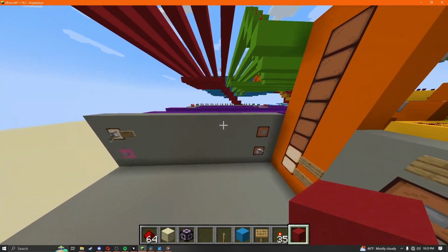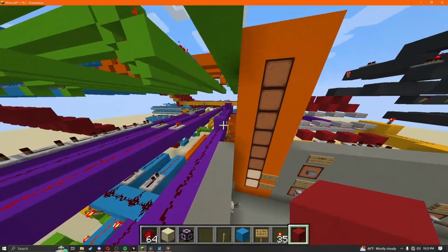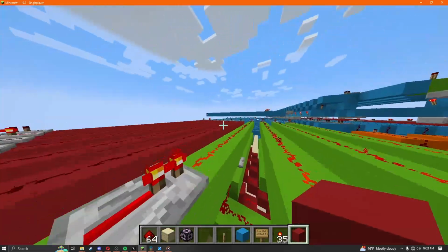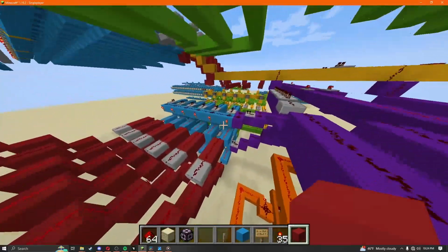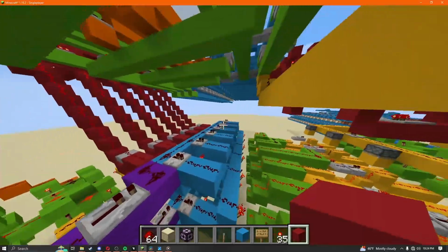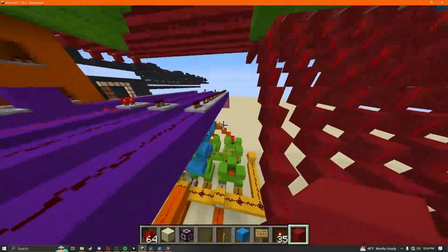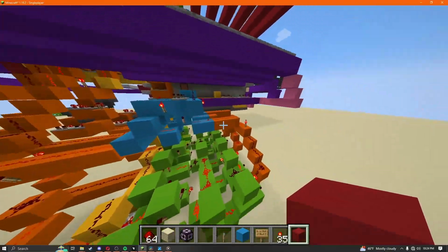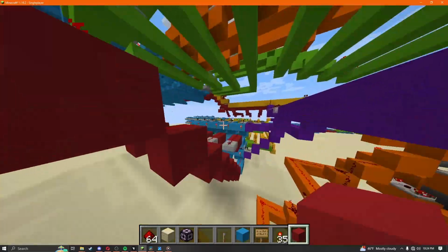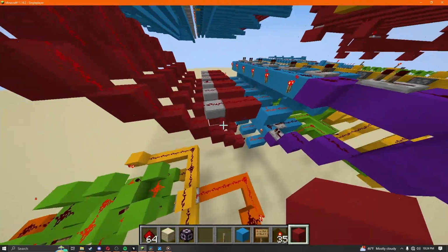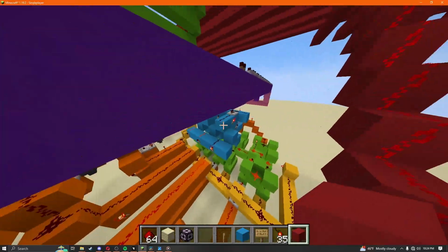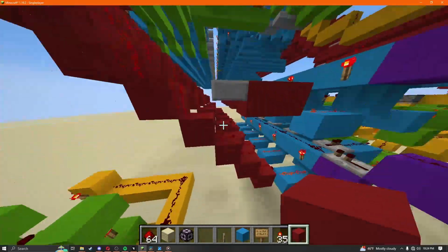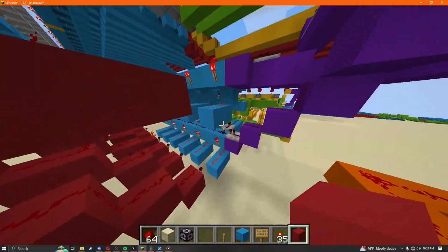How do we execute an instruction? To start with, we're going to read the value from the currently selected register down, and it's going to get stored into a temporary register. After that, we're going to decrement the counter via this mechanism, this monstrosity. And we're going to save the second value down here. So first we'd pull the 2 down, we'd decrement the program, and we'd store the 7 down here.